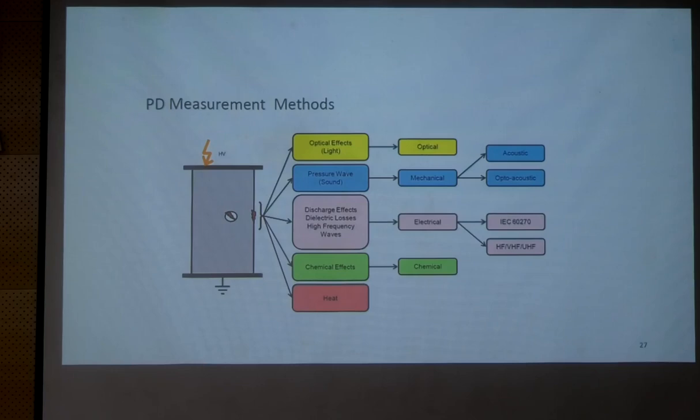As we see in transmission lines, at the tower structures there could be sharp points. During rainy seasons the surrounding medium is ionized, and if it crosses the disruptive voltage level, you will get corona discharges. We can see a glow discharge. The manifestations of these partial discharges differ: visible discharge, a hissing noise, and